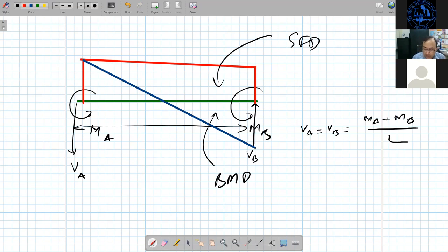Okay. Now, due to dead load and live load, the shear force is changing. It is linearly varying. The shear force due to dead load and live load is maximum near the joint. So the total shear force, which occurs due to earthquake and dead load and live load, will be maximum at the support near the joint. That will be maximum. And bending moment will be maximum because the earthquake bending moment is maximum near the joint. So bending moment will also be maximum. Shear force will also be maximum near the joint.